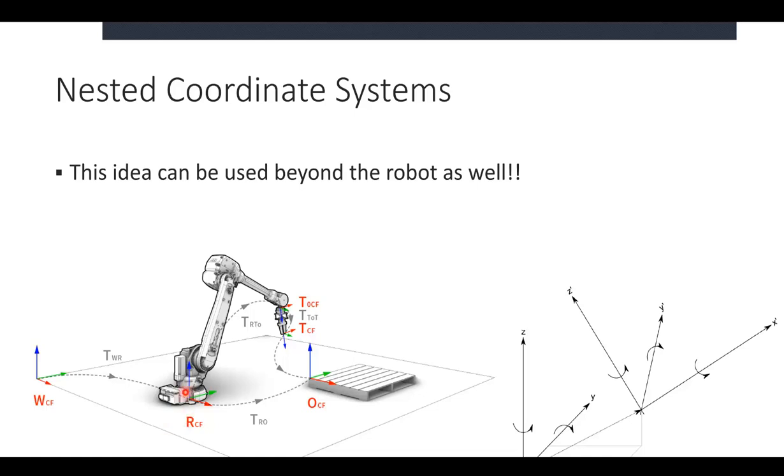So in order to go from the coordinate frame from the base of the robot here, where the laser pointer is, all the way out to the end effector, we do want to know the transform between those two. It's less likely that we're going to explicitly be dealing with the transform up to this intermediate joint, because most of the stuff we're going to do is either from the perspective of this base, or much more likely the perspective of this end effector out here. But that's a good question.